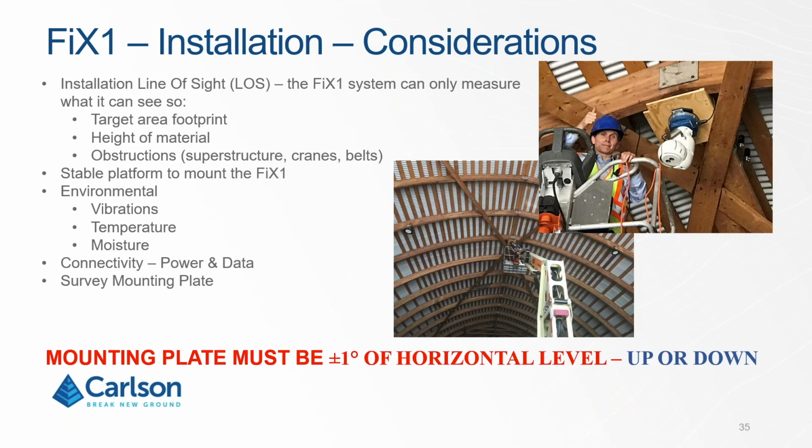All right, so installation considerations. As you can see here, this is one of our good distributors installing one of the FiX1's in a salt dome that we have for testing. But what do you have to consider when you're installing the FiX1? So you want installation line of sight. The FiX1 can only measure what it can see. So it's very important to take a look at what your target area footprint is, the height of the material.